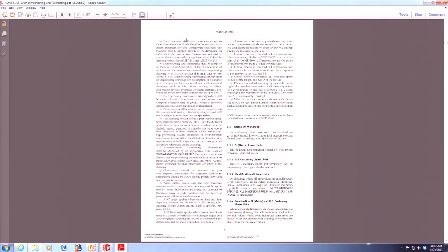All of them have a tolerance, but that one doesn't have a feature control frame anywhere giving that tolerance, because there's no positional. A datum is not a physical object or a physical surface. It's a theoretical surface, and that's what you're getting into with your datum target. You might have to add a note to say it's theoretical at that point in time, and you're probably dealing with gauging companies.